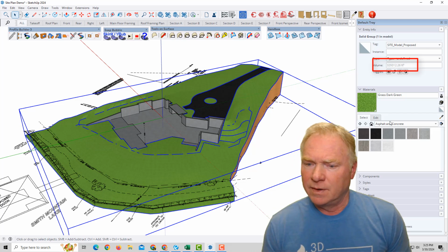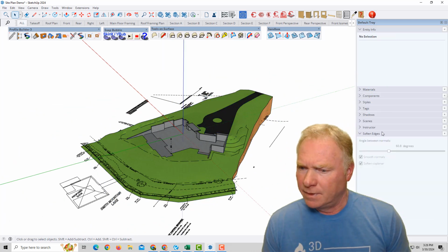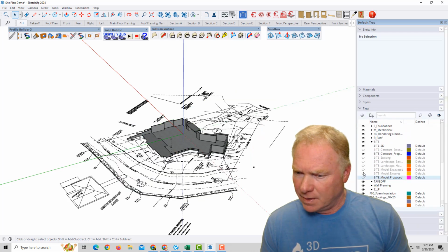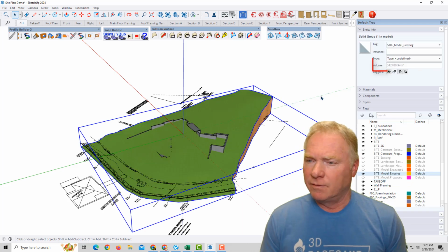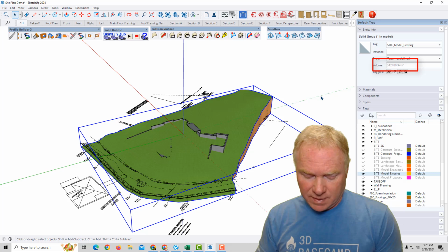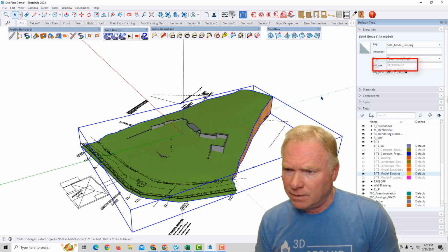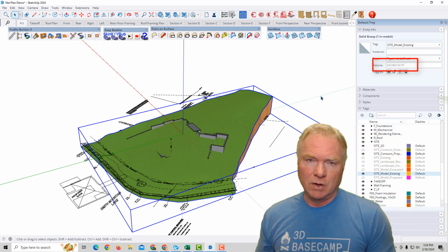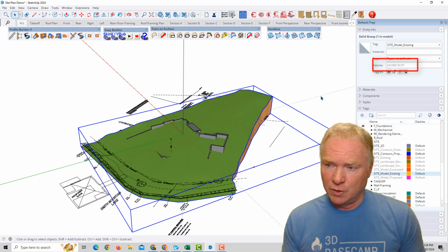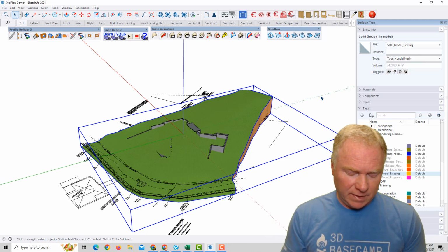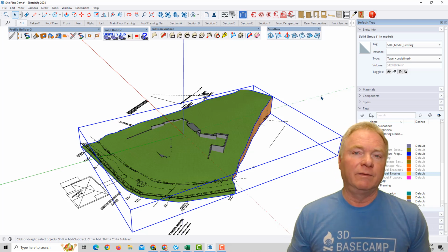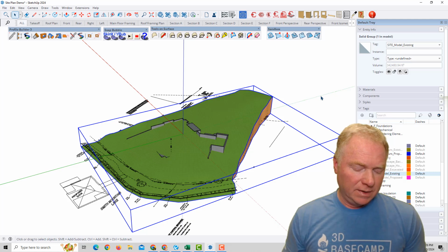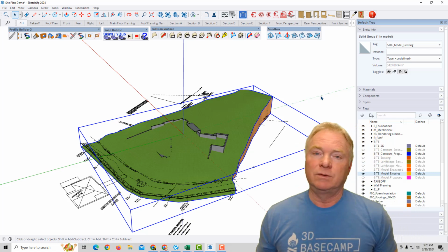All right, and then I'm going to cut this off. And let's cut off the proposed site, cut on the existing site, and its volume is minus 342,481, rounding it off, is 13,000 cubic feet, excuse me. Divide that by 27, and that's 487 cubic yards of dirt extra. Divide that by, say, I don't know, 15 on a truck. That's about 30 some truckloads to haul out of there.